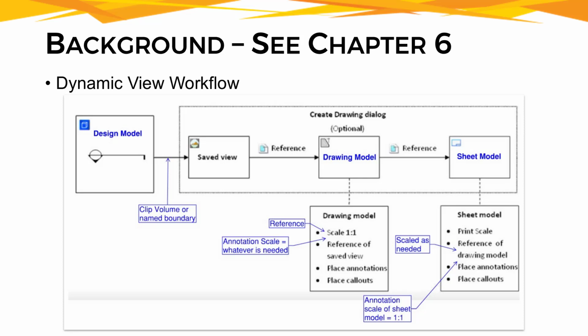As a note, the FDOT borders should never be added as a reference or placed as a cell in the design model anymore. The border is set up to be automatically placed within a sheet model.